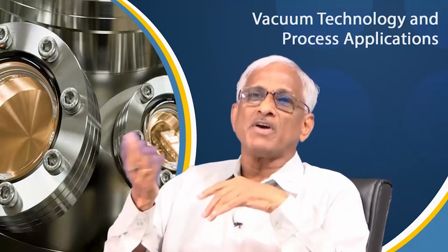So, we are utilizing the thermal insulation concept of it. That is good enough if you have 10 power minus 3 thermal vacuum. You will not get more advantage at 10 power minus 6 or minus 7, because the residual gas conduction, as well as the conduction heat transfer and radiative heat transfers, which are anyway there, are dominant. So, you will not get further advantage of thermal insulation when you go below 10 power minus 3. So, these concepts have to be understood when you talk about thermal and electrical insulation.